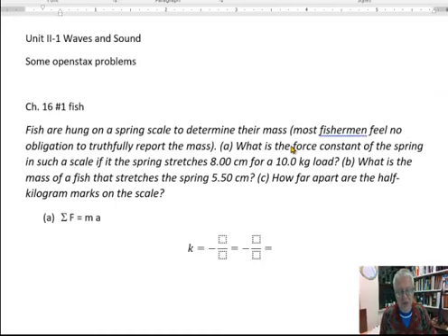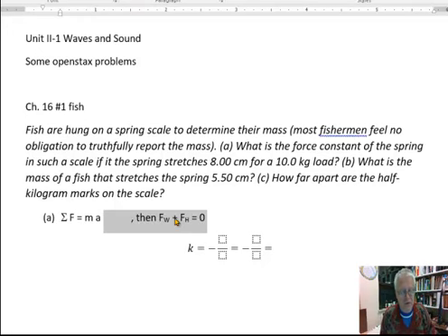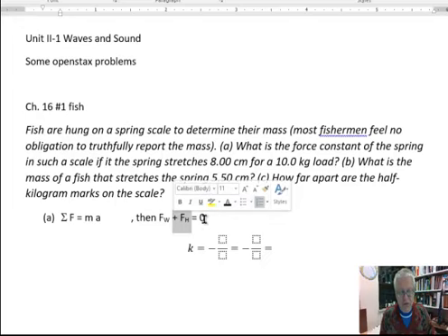So here you have to envision a spring that is holding a load, and as it's holding a load, Newton's second law applies to that. I already hit some text here, so I'm going to turn this back on. And so the sum of the forces on that load that is hanging there is then the weight, and then the restoring force, which is Hooke's force. And because the whole thing is supposed to be in equilibrium, that's why we see a 0 there.